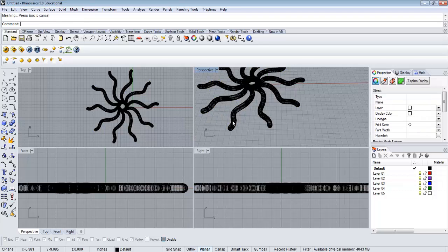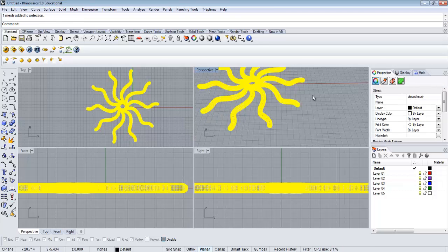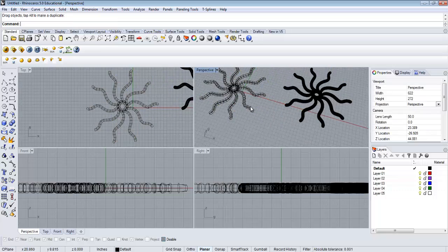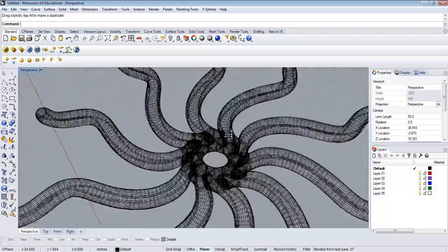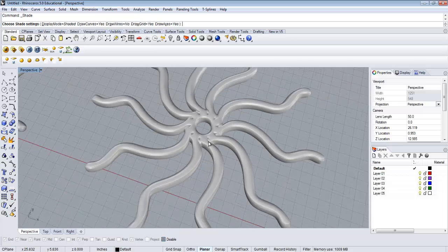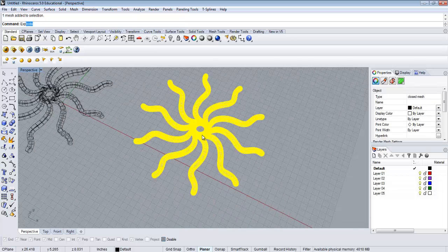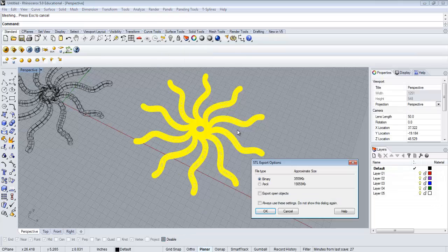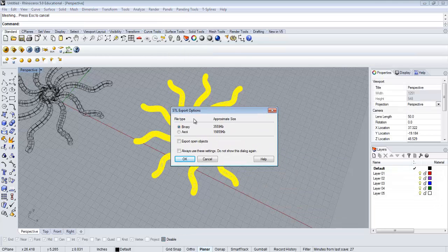So we'll go ahead and mesh that, and then when we select our mesh, automatically it's going to be a closed mesh. And so you can come in here. You can just leave those mesh settings like the one I just showed. This is a fully 3D printable object, so you can just take this and export it. You just select that, export as an STL, stereolithography. From there, save, and it's going to prompt you if you want to do it in binary or ASCII. If you just want to do binary, it's a little smaller file, a lot easier for you to upload.